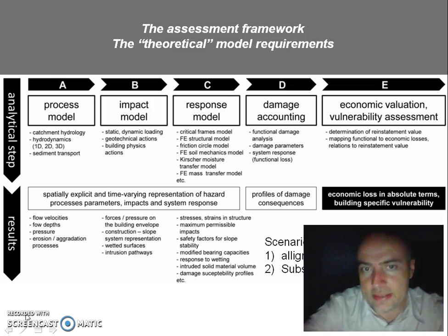Also for soil mechanics, finite element models are now available that enable quite detailed modeling of the mechanical behavior of the soil. In relation to building physics, there are a lot of models also available that allow us to retrace the moisture dynamics throughout the wall, and also other mass transfer processes. The response normally is accounted for through the quantification of stresses and strains in the structure.